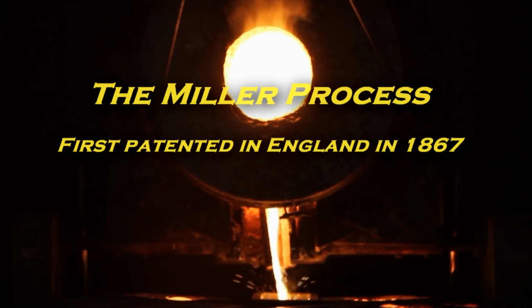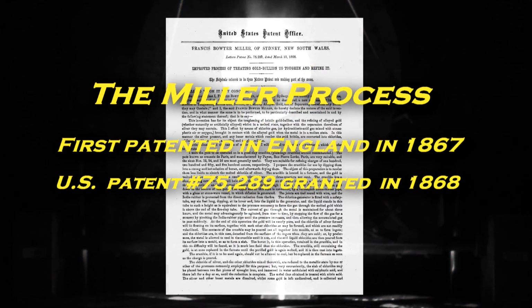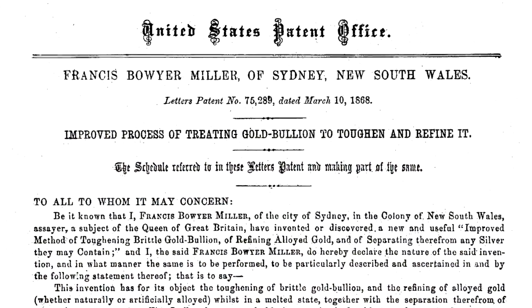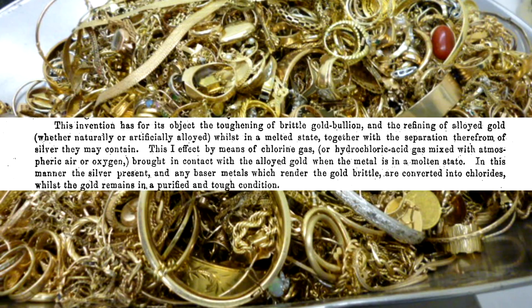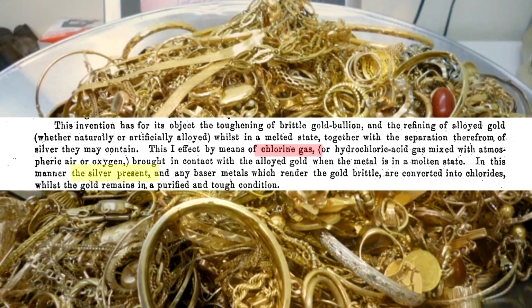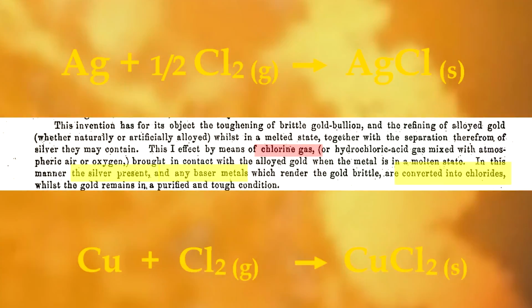The Miller process was patented in 1867 and is still a very effective process for stripping out silver and base metal impurities from high-grade gold alloys such as doré produced by many mining operations and high-grade jewelry scrap. This is done by bubbling pure chlorine gas through molten gold, which reacts with the silver and base metals, forming chloride salts.